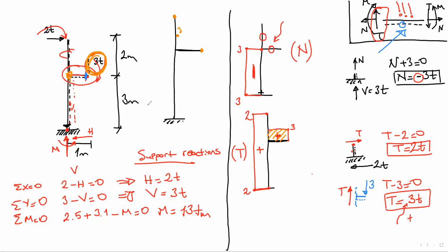In cantilever, if you connect these 2 points to each other, we have a right triangular change. This is the cantilever moment, negative. That means tension occurs at the top.